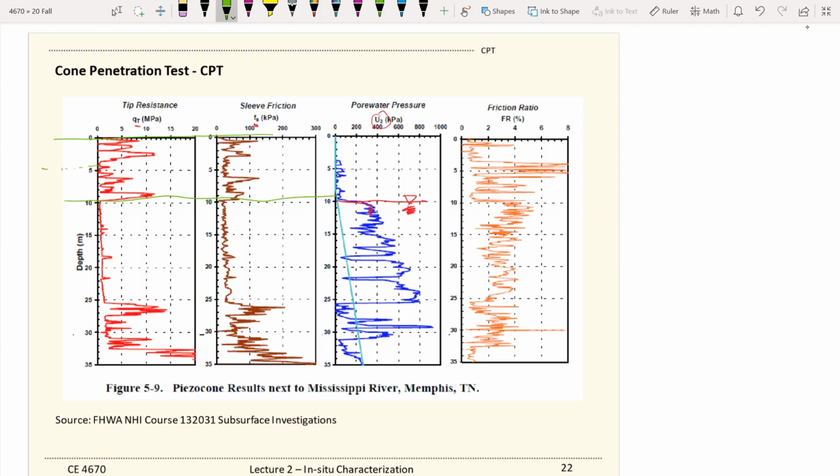Or maybe within the first layer, you may be able to find more sublayers. And very clearly, this is another layer with all this tip resistance and side friction right there. And here maybe your third layer. Here maybe the fourth one. So CPT will record all this data, and there will be an engineering procedure on how to convert all these measurements into what we want.